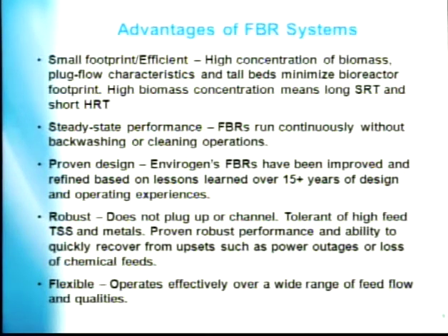FBRs can run continuously without backwashing or cleaning operations. It's a proven design. I'm going to show you some examples, but we've been building this system for over 15 years. We have over 40 systems installed, full scale. Just not drinking water per se, but some that produce drinking water. I'll talk about that as we move along. It's robust, the system won't plug up or channel, and it's tolerant of high feed concentrations if you have a shock load, because you have this recirculating water phase that helps fluidize. You can actually buffer through that recirculation.